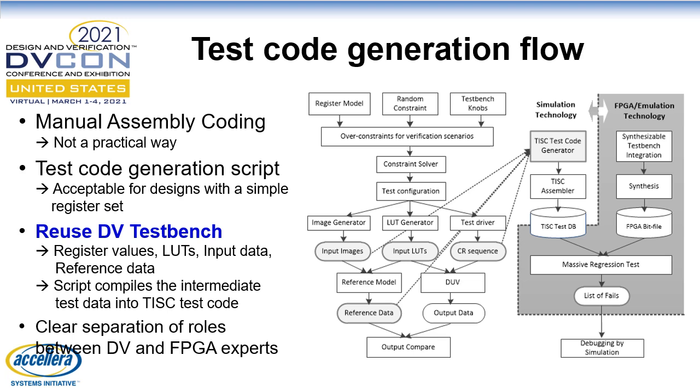From the team management viewpoint, a methodology that can separate the roles between DV and FPGA was highly demanded. The proposed test bench architecture guarantees perfect reproducibility of test behaviors because it is a closed system while the test is running. So there is no need to debug issues using FPGA systems directly, because the issues can always be reproduced by simulation. For FPGA owners, sharing the test identification number with DV engineers is enough. So both DV and FPGA engineers can stay in their safe zone.